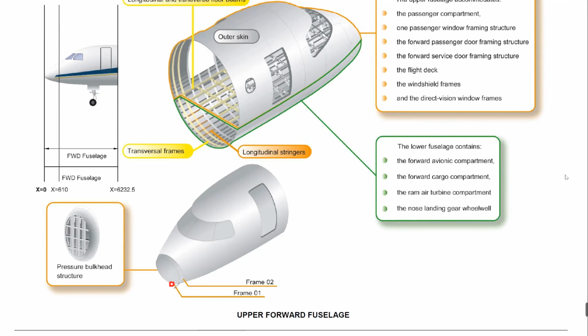And we already had this frame number 1, yes, just behind the radome is frame number 1, then number 2. So I said, oh my god, this is not possible. They were flying with a lot of air leaking, because the hole was big, so I could put my finger in the hole. It was an amazingly big hole because of the lightning strike.